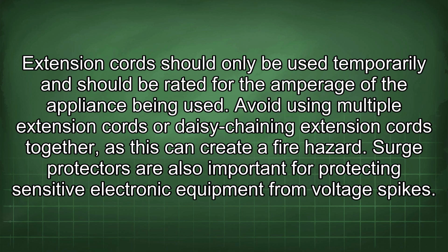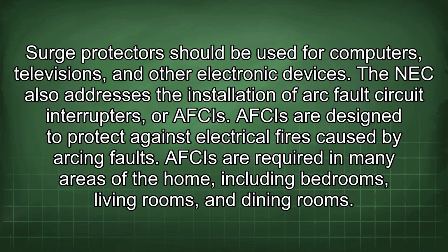Surge protectors are also important for protecting sensitive electronic equipment from voltage spikes. Surge protectors should be used for computers, televisions, and other electronic devices. The NEC also addresses the installation of arc fault circuit interrupters, or AFCIs. AFCIs are designed to protect against electrical fires caused by arcing faults. AFCIs are required in many areas of the home, including bedrooms, living rooms, and dining rooms.